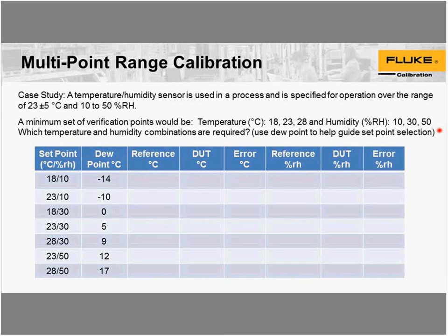There are others that we calibrate and find that the calibration performed is not out of tolerance, but now that the humidity has gone down, they show out of tolerance. Oh, that's interesting. I would definitely check those RTDs for leakage.